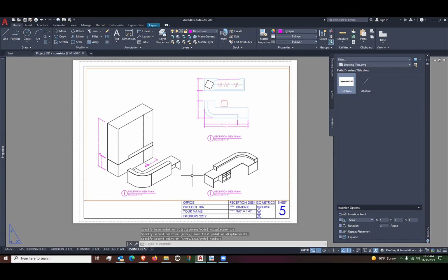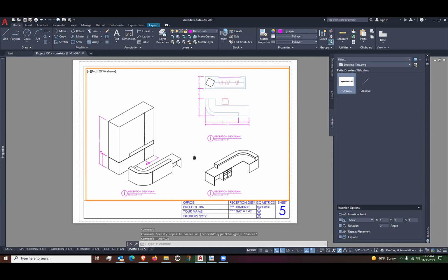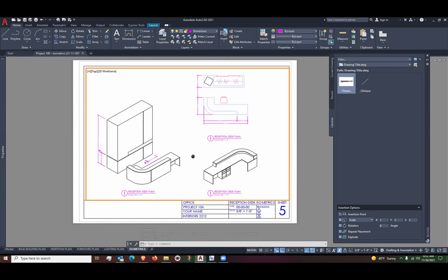And I think that these are a little bit close. So what I'm going to do is I'm going into paper space now. Let me unlock this. And now I'm just going to pan. I don't want to change the scale, but I'm just going to pan, and actually that looks a lot better right there. I just want to get a little bit of space, a little breathing room here, particularly if you have some dimensions here. I just want to get some breathing room between the actual detail and the call out or the title.